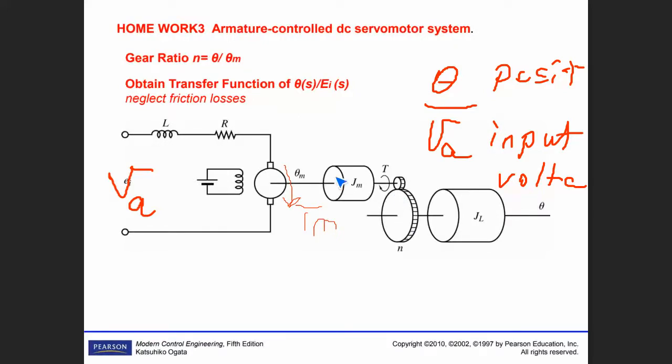Electric machine speed is approximately 10,000 RPM, which means approximately 1,000 radian per second in mechanical. Then we reduce the speed to 1,000 RPM, revolutions per minute, and send it to the differential.